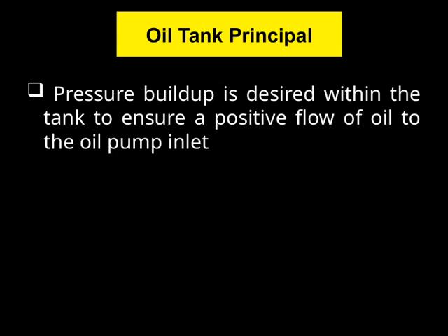Pressure buildup is actually a key aspect of maintaining proper oil flow within the system. By creating a certain amount of pressure inside the tank, we ensure that oil is pushed consistently and reliably towards the oil pump inlet. This positive pressure helps prevent issues like air pockets or inconsistent flow, which can affect overall performance. When the pressure is maintained correctly, it guarantees a steady supply of oil, supporting the efficient operation of the entire lubrication system. This is crucial because, as we've discussed earlier, a reliable oil supply is fundamental to the health and longevity of the machinery.